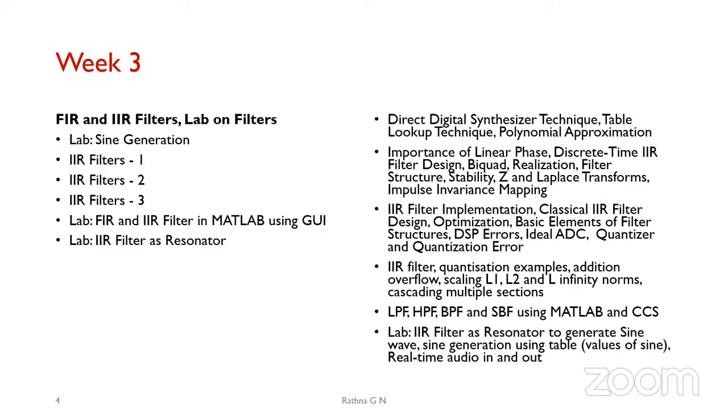And then the second stage of error is when we are using the DSP processor. Based on the design, direct form or indirect form, and how we represent our coefficients, coefficient quantization is going to happen.